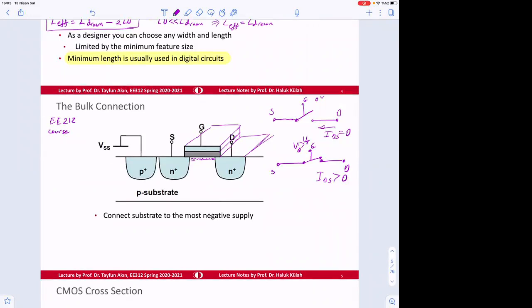So in order to make a gate, for example, we will say that this is now a resistor, and this is VDD, and this is our transistor model, or symbol, the MOS transistor. Here, if the input is 0, this NMOS is off.